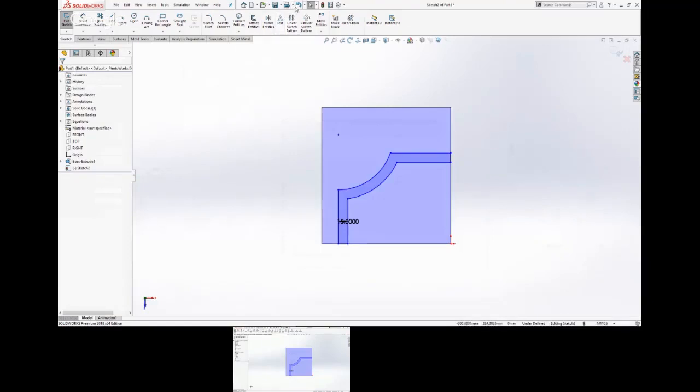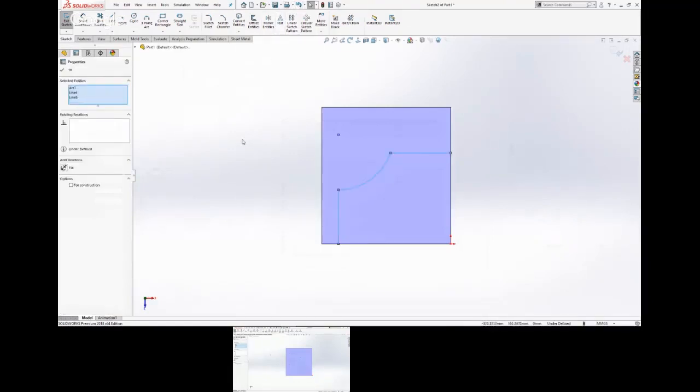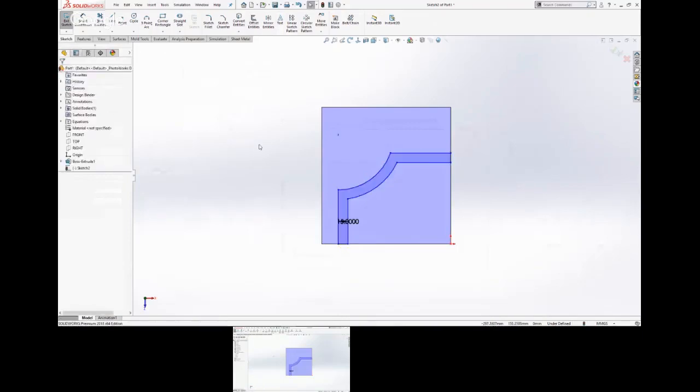So if we undo that, I just window selected, hit sketch offset, and then over here, if it's 15 millimeters, you hit cap ends, and make sure it's lines. If it's arcs, you see what it does in the preview? It gives you the arcs out here on the edge. But since I chose lines, and because of where they terminate, they're fully defined at that point. So that's my sketch as a whole now.